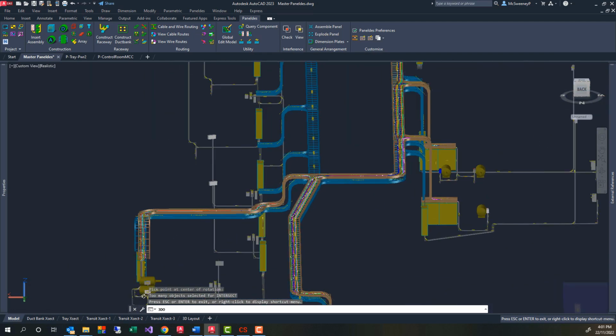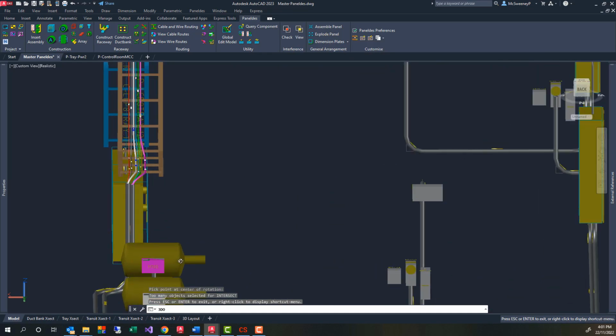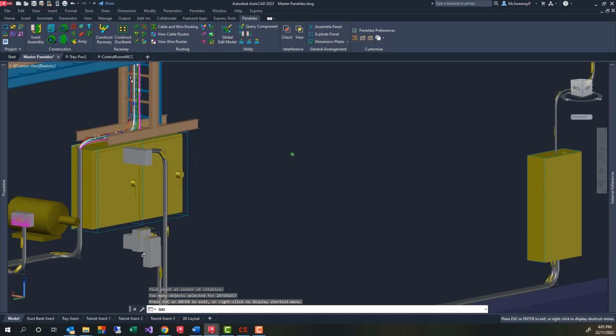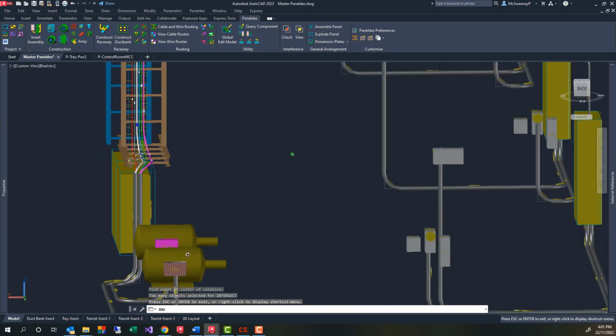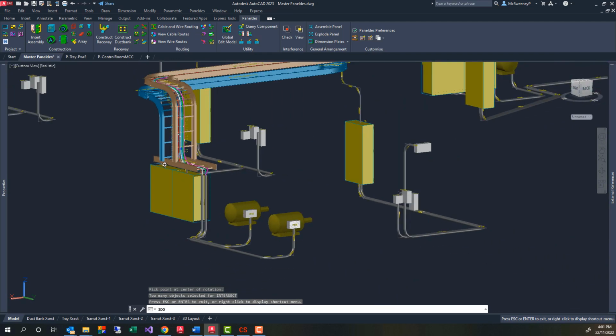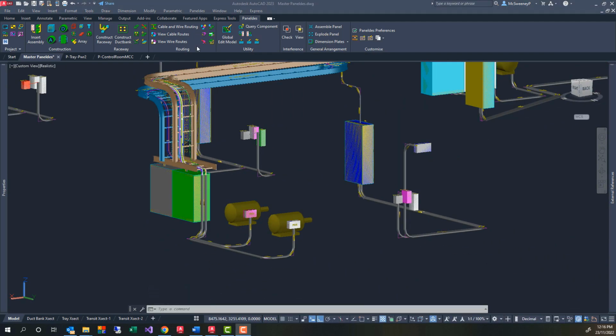I should mention waypoints. Waypoints guide a cable around an area or obstacle by naming one or more trays that the cable must go through. Sometimes this is necessary, for example in a cable redundancy situation. Note, any manual intervention will be very slow compared to automated routing.